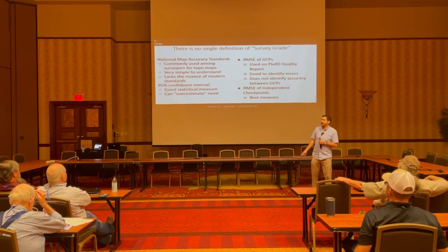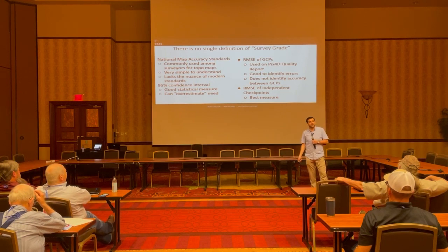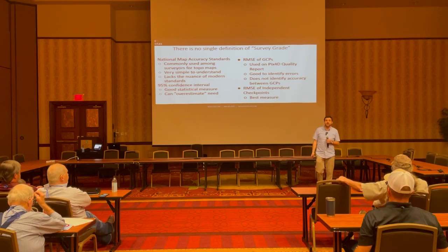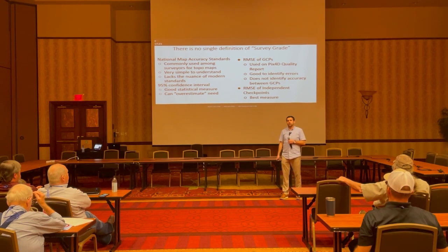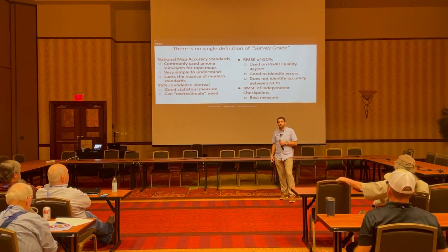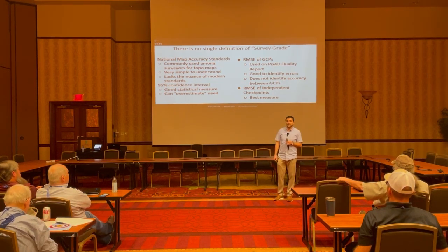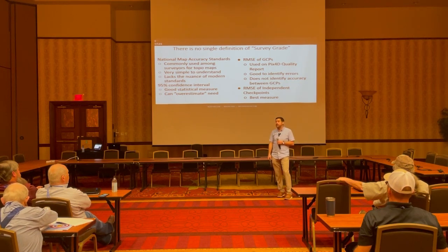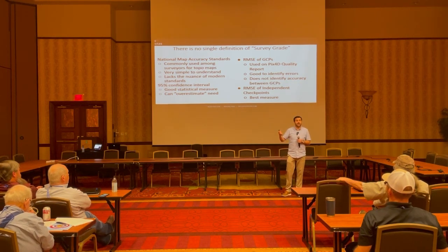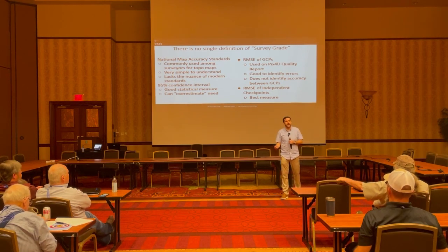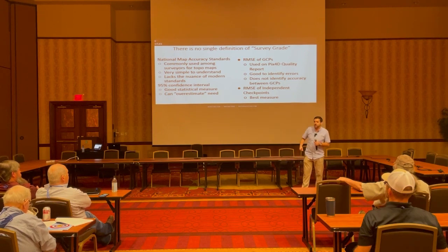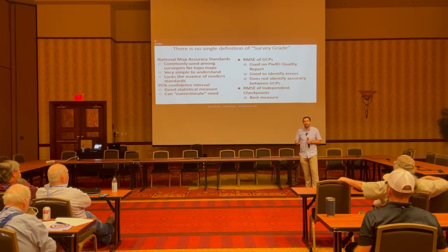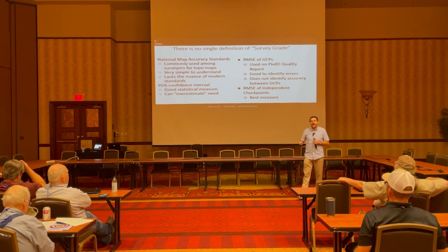And even when I say survey grade, I say 1/10 of a foot, which a lot of people consider survey grade, but it depends on what you're doing a survey of. Again, if you are doing a railway survey, 1/10 of a foot might not be good enough. Or if you're the Department of the Interior and you're measuring 50,000 acres of rural Wyoming, then survey grade is 10 feet. And if you're within plus or minus 10 feet, you're great, and that's a survey. And that's actually survey grade because they know what their accuracy is for the needs of the project. So if you ever hear someone say survey grade accuracy, you should probably raise an eyebrow and say, what do you mean by survey grade? How are you measuring that?